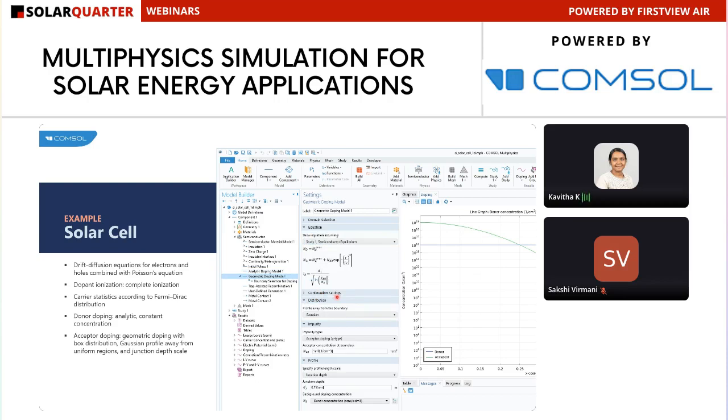Then you can add Gaussian doping decaying away from the surface of the device to form the PN junction. The geometric doping model is convenient for setting up this kind of doping profile. Next, here you can also define the acceptor doping concentration.